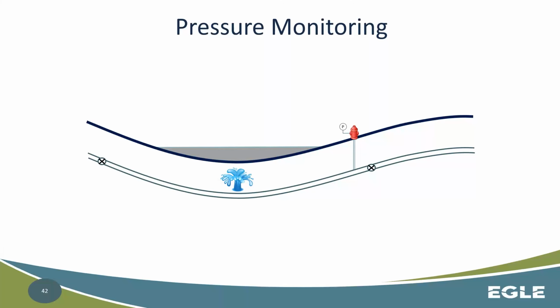So just be aware that if you have, we'll call them crossings, around water bodies, you really need to make sure that from time to time you check the pressure associated with the hydrant before or after, which, by the way, a hydrant is almost always required in these scenarios. The other potential you can have is a meter requirement either before or after a crossing, so that you can see that water is flowing through this location as you would anticipate, and that there's not some change in condition over time here.